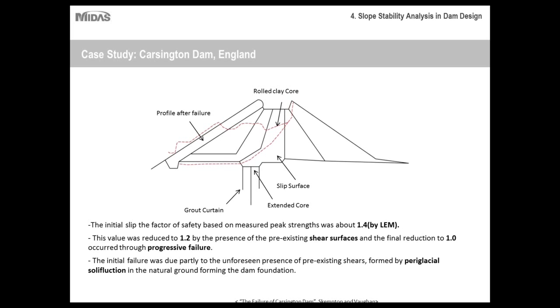As you can imagine, when water freezes, it expands. So just imagine all of the water in this dam expanding over the course of a winter. That will cause some breakage or some shear forces within the dam. And then imagine all of that water melting during the spring and maybe seeping out. Those shear forces are going to be increased. Imagine this happening periodically over a couple of years or even a couple of months. That's going to eventually cause so much shear within the dam that it failed.